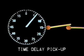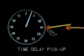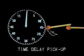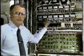There are two types of timer relays used in the electrical system. The time delay pickup relay waits for a preset time period before transferring contacts. When the relay is energized, a timer begins. When the time period is up, the contacts of the switch will transfer. The gas purge time delay is an example of the time delay pickup relay. When it is energized, a 10-second timer begins. At the end of the 10 seconds, the relay contacts close and energize the primary fuel valve.